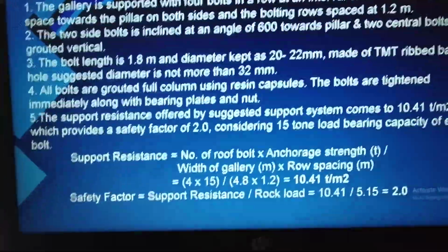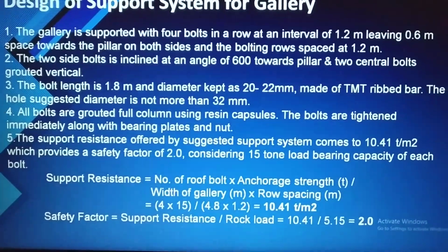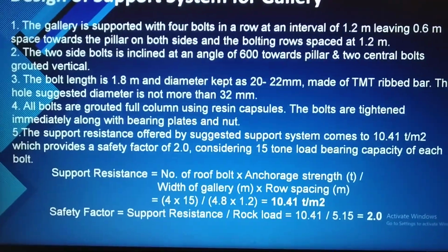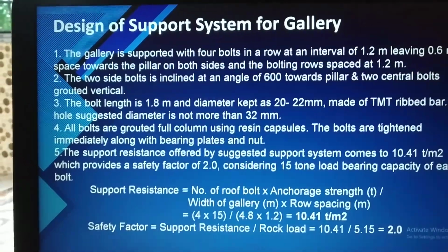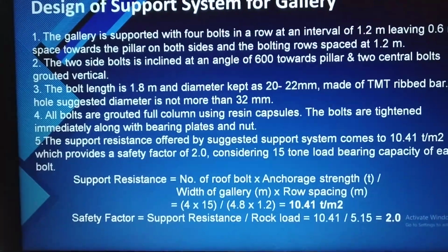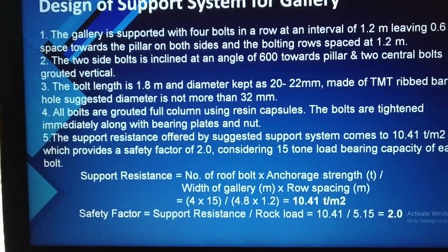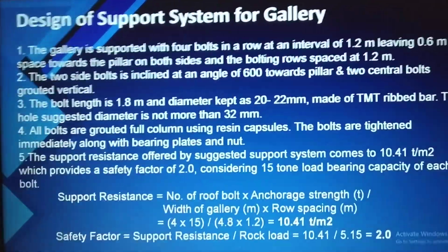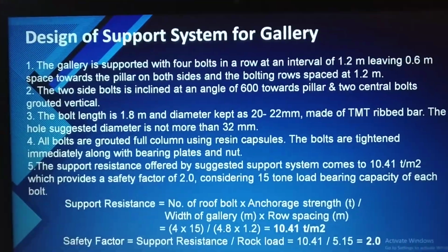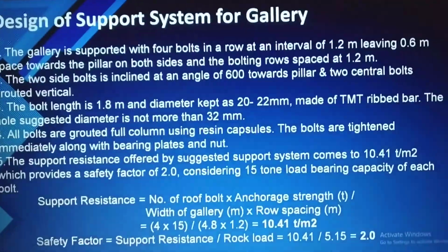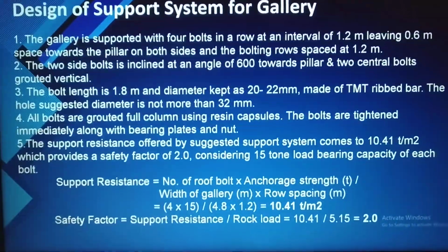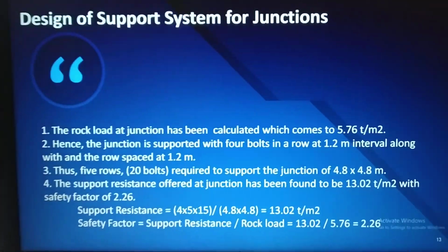As you can see, earlier the safety factor that we calculated for the pillars was less than 1. So after having the cable bolts grouted inside the roof, we now got the safety factor as 2. So this is how we can examine how a support system will help to prevent the number of accidents that have been occurring in the mine and can help our workers to have safe operations inside it.